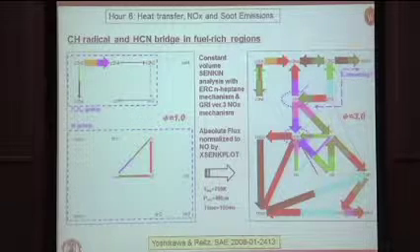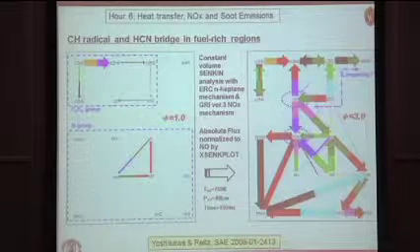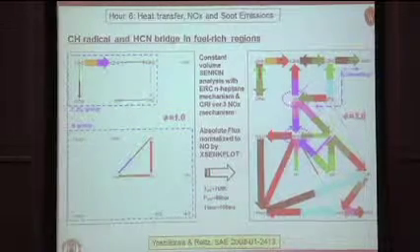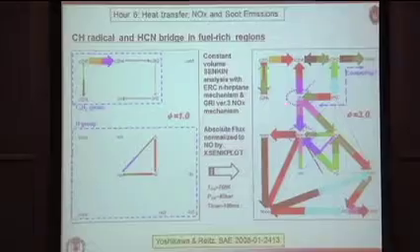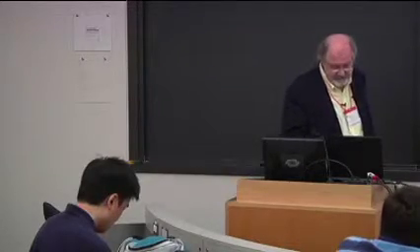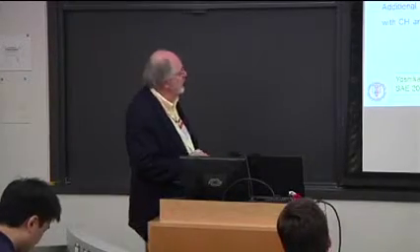So there's essentially a very loose connection there. But if you go to a very rich mixture, equivalence ratio of 3, for example, you find that there's actually a competition for the CH radicals between the soot through the C2H2 path and HCN, which eventually leads to NOx formation. So as you get to richer mixtures, you need to have more crosstalk between your soot model and your NOx model, which we thought was kind of interesting. But the requirement then is to really extend your NOx mechanism.